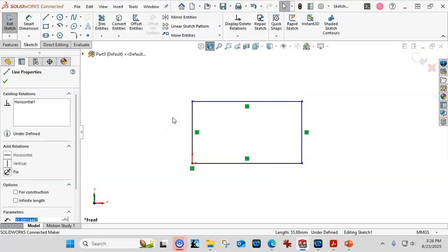So as you're starting to observe these, I believe the sketch relations are off. So let's go ahead and turn those back on temporarily, because that is the default. If you've just installed SolidWorks, you're probably looking at something like this. So it is telling me that I have a coincident, I have a vertical, I have a horizontal, the vertical, the horizontal. Those were all applied automatically because of those little yellow boxes. All right, if I miss, and we'll miss plenty in the course of the class, I'm going to pick one of those lines and tell it that it's horizontal or vertical.